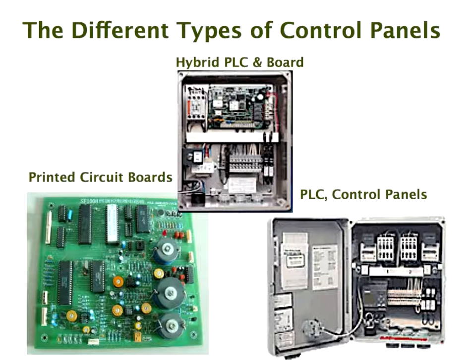We have known panels that have been designed in a manner that we would recommend, where you end up with a demand dosing situation, where you take the effluent directly from the treatment plant and pump it straight into the drip system, and you rely upon the operating control of the treatment plant and the flow of the treatment plant to determine the flow into the drip system.